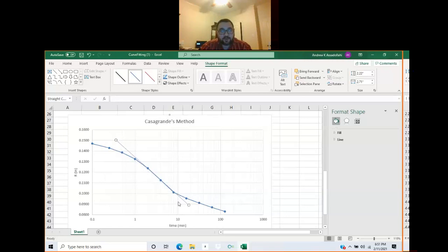Okay, you can move it around, and I'm going to change it to a red line just so we can see it a little bit more clearly. And so that's going to be through the primary consolidation data, and then we're going to add another tangent line through the secondary consolidation data, which is right around here. I'll make that red as well. Remember, secondary consolidation is occurring right here in this neighborhood. It's where the data changes curvature and it becomes more curvy.